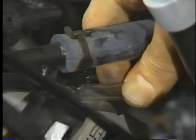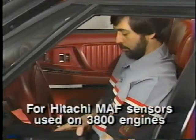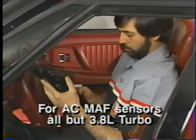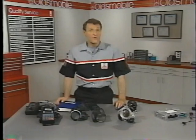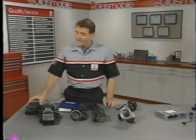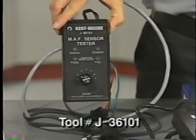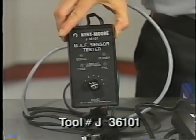This tester performs dynamic testing of the sensor with the engine running. It can test the Hitachi sensor used on 3800 engines and all AC MAF sensors except the one used on 3.8-liter turbo engines. There is one other tester available. This is the static MAF tester. It works only with AC MAF sensors, and it performs the test with the engine not running, ignition off.